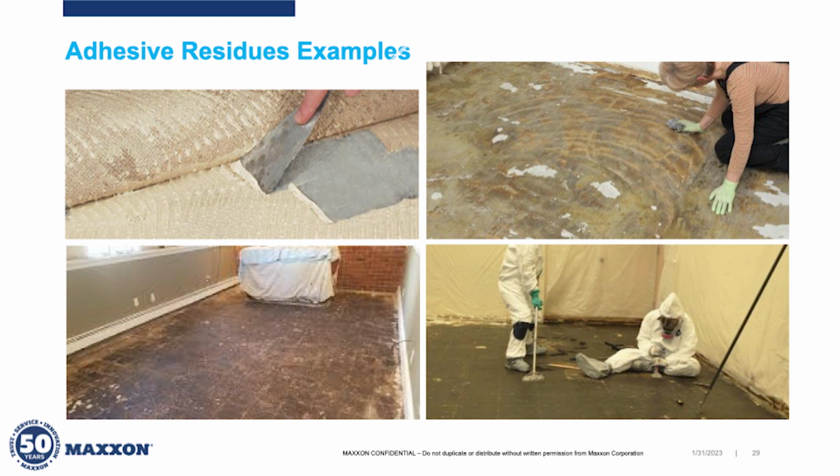Existing pressure-sensitive adhesives, if they're left uncovered for long periods of time, let's say the old floor covering was removed at the beginning or the front side of the job, then you're going to expose the surface of that adhesive to all the other job site debris, which can fall to the surface of that adhesive and bond to it. Things like wire clippings or dust from drywall or just drywall debris in general. Just making that whole removal or cleanup process before the new floor is put down more difficult and more costly, because there's different things that have to be done here.